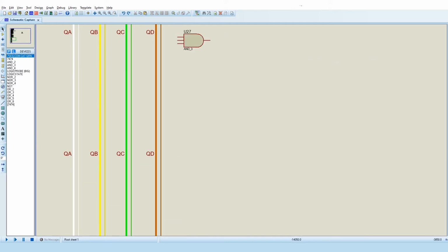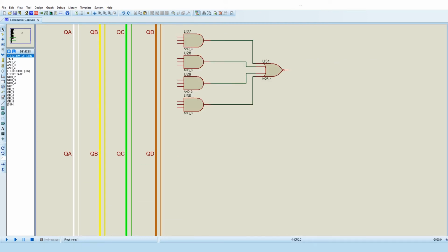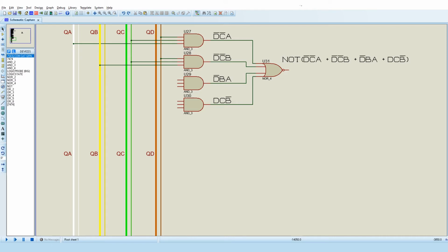Just two more. These just came from the Boolean expressions that we worked out. We just wire them up from the outputs of our counter, which will cycle through all the numbers for us. D, C, not B. And that we need to label, put a wire in and label it as F, then label the segment on the 7-segment display as F as well.